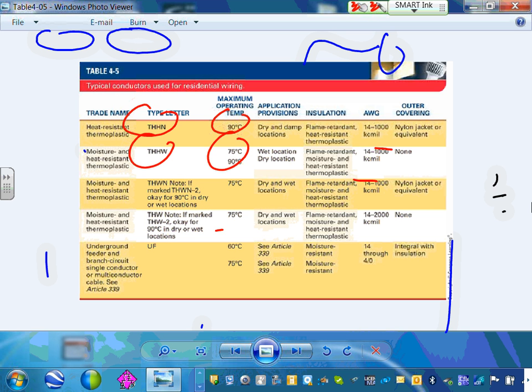There's a bunch of UF cable. Yes, good one. UF cable, guys, if you're using it indoors, you treat it like Romex, basically, and you use 75-degree for the rating and so on. UF cable looks like NM cable, except when we use it direct buried in the ground. That's the key for it. We treat it exactly like Romex, except you can bury it.